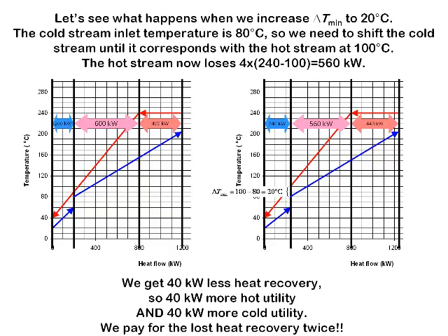It's a double whammy. So by avoiding the heat recovery that we could get with a delta T min of 10 degrees, we're getting less heat recovery. We're paying for that twice in terms of more hot utility and more cold utility. That's worth thinking about.